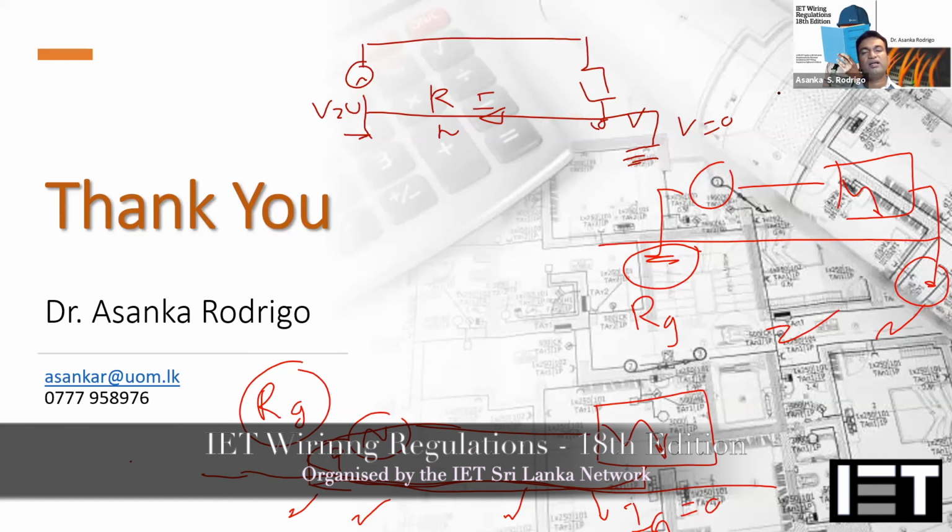RCDs are generally used at the end equipment or end level, where fault currents are generally lower because of the high impedances at the end level. When you calculate the fault current at the end equipment, it is generally low, so the RCD can handle it without any problem. The RCD gives you a short-term breaking current, and if the fault is within that breaking current, you can handle it.